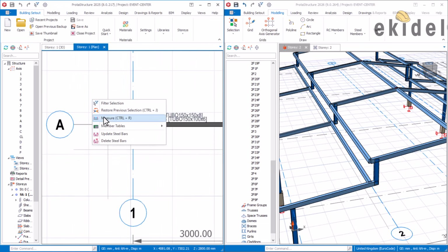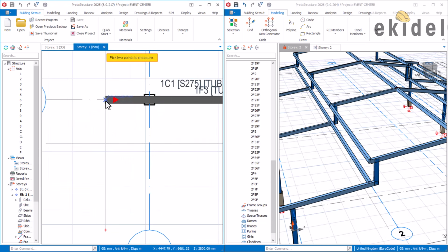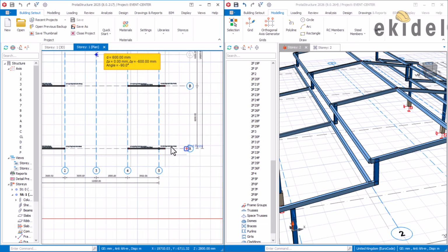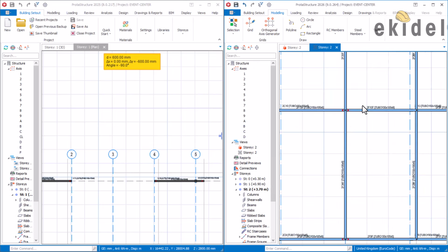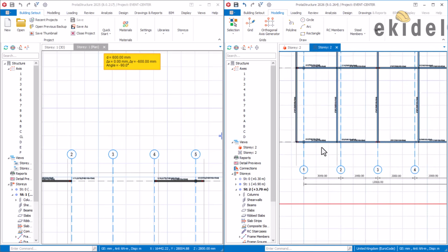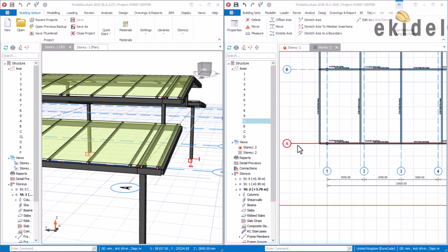This other one here, come here, measure here, and then we click from center point to here. This is 600, correct? So 600 again, front and back, and also at the back here too. So we have to come here too now and then offset the same thing. Now this takes this off front to be a cantilever. After we do that, then we come now and offset this here by what? Let me keep this one here by 600 millimeter.